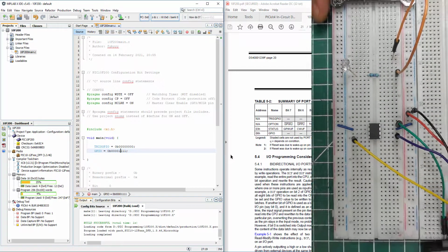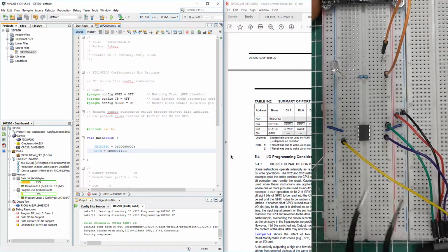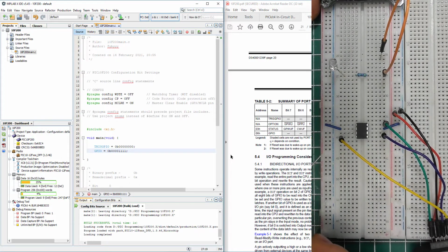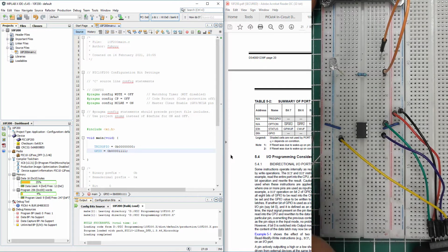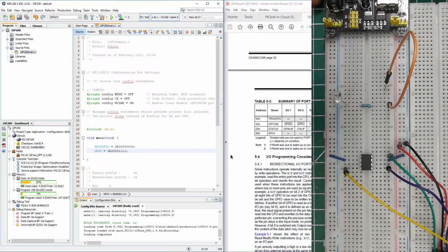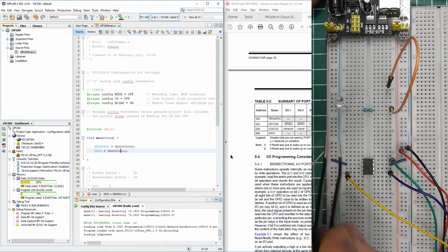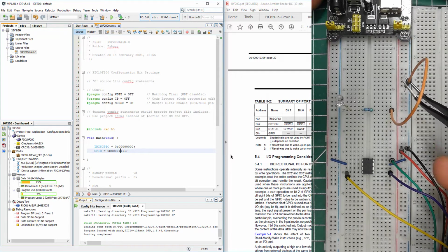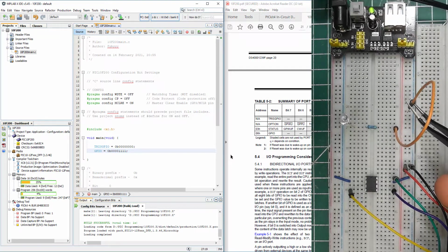What we're going to be looking at is those pins, the ones that we can use, to see if the programming was successful. And we've got 5 volts there. Now to check if everything is okay with this LED and the resistor, I'm going to take this pin and source 5 volts straight from the power supply, which is switched on.